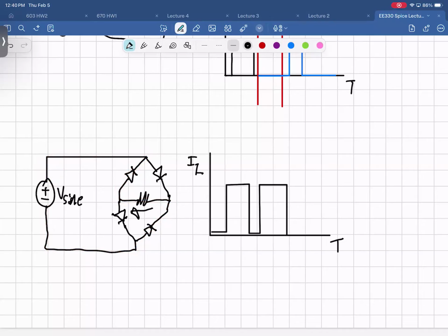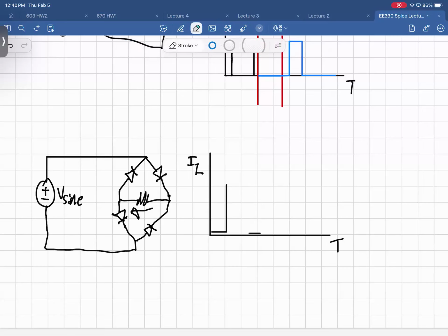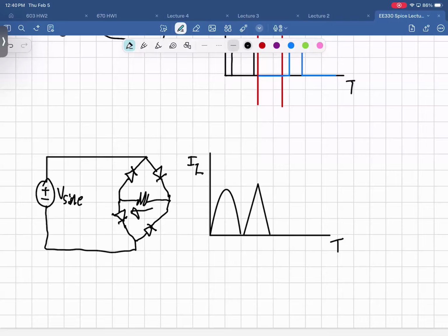Question? Can you explain why it says square root instead of? Yeah, this is with the assumption that the diodes are fully conducting or not fully conducting. It's a really simplified model. So you're right in that you would actually see something more like this. That's not supposed to be a triangle. Also not supposed to be a triangle. We're just gonna deal with my bad handwriting, I guess. Yeah, so it looked like two humps instead of two square waves.